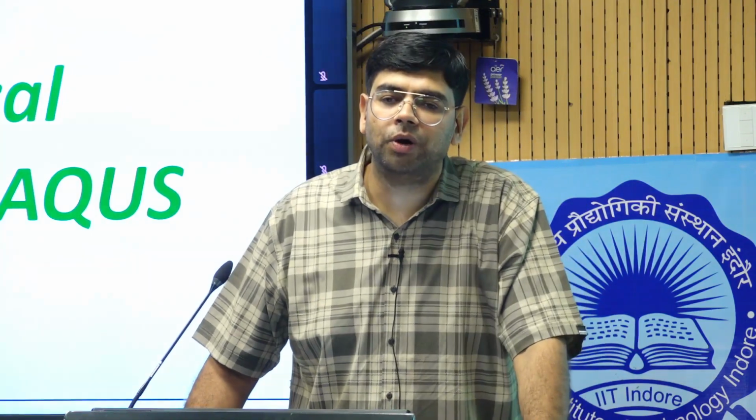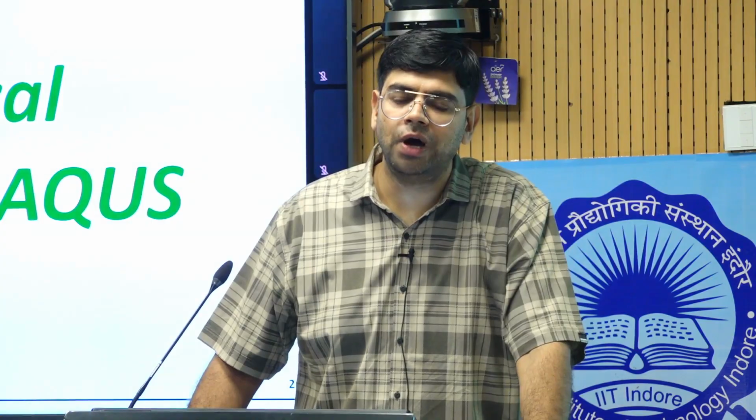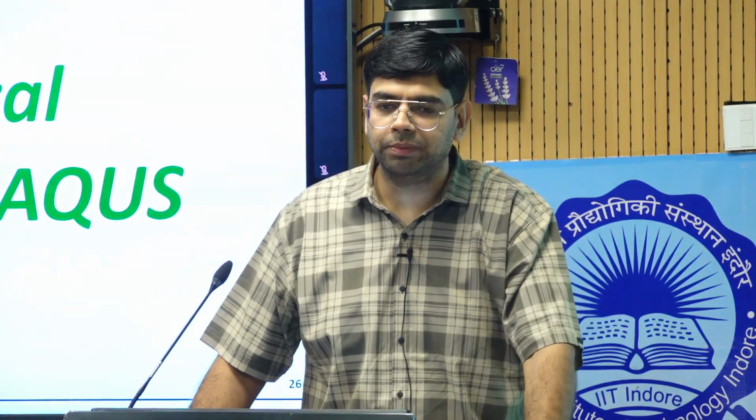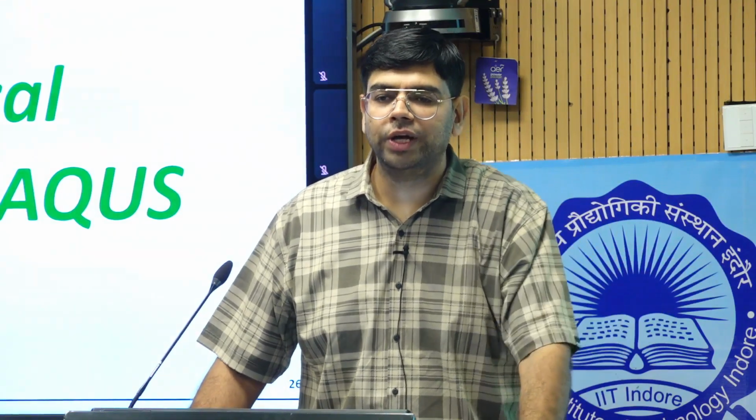Second thing, after defining the geometry, is the material. You have to define the material properties of the individual components. For example, we have the dielectric elastomer membrane, frame, and stiffener. In Abaqus, different properties are available.